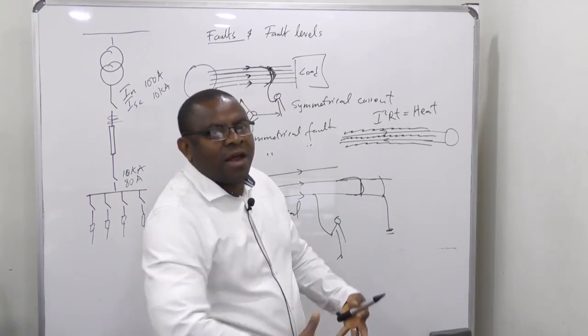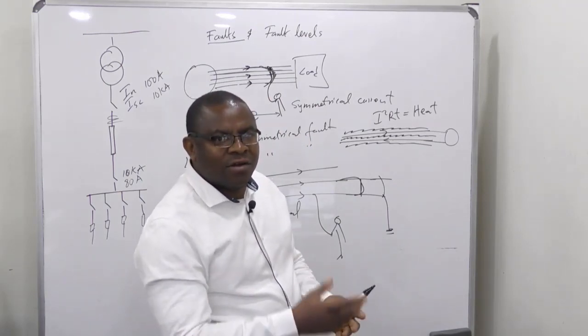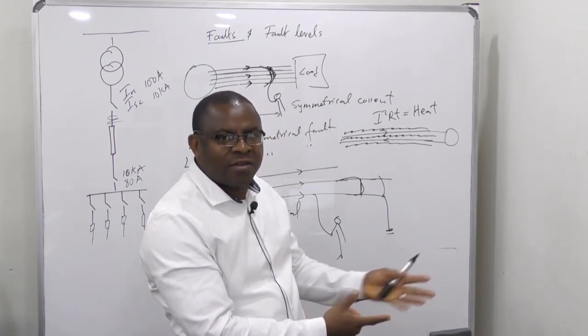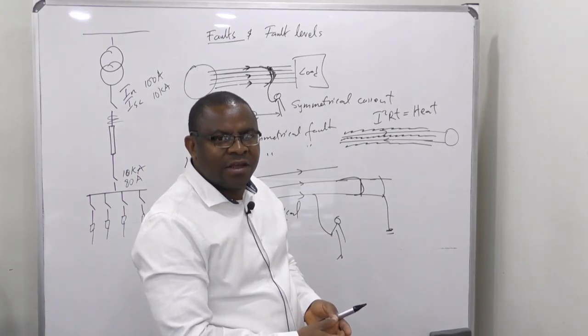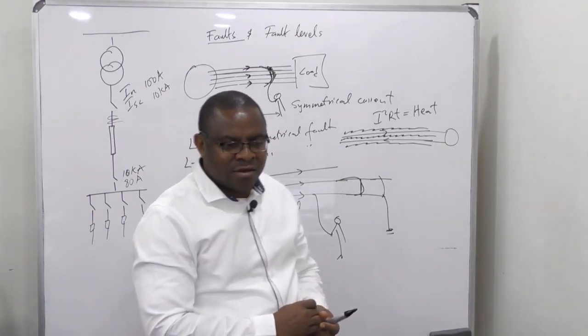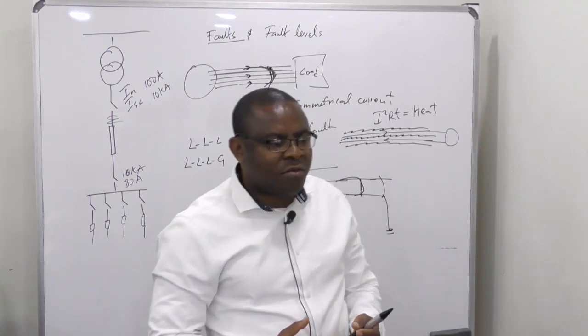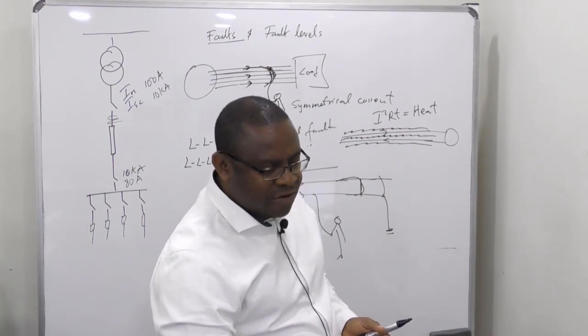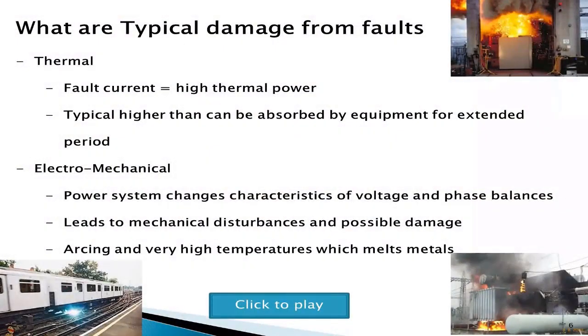they will think that they are powerful. So you have your screwdriver, you want to change a socket, and all of a sudden the screwdriver touches live and neutral, and then you hear a sound. Which is not good. So we must try as much as possible to isolate our system before working on it, because we don't want such high thermal power as a result of a short circuit to destroy our equipment or harm the technician.